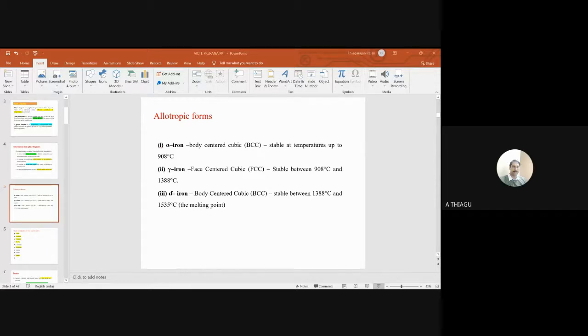Next, we move to the iron carbon diagram. It is very, very essential. You can get a lot of questions from this particular area. We already studied the iron carbon diagram in your second year or maybe in the first year. So now once again we have to revise, or just recollect the information we have studied. First of all, it comes under a phase diagram because different phases are formed. It is a graphical representation of carbon on the x-axis and variable temperature on the y-axis.